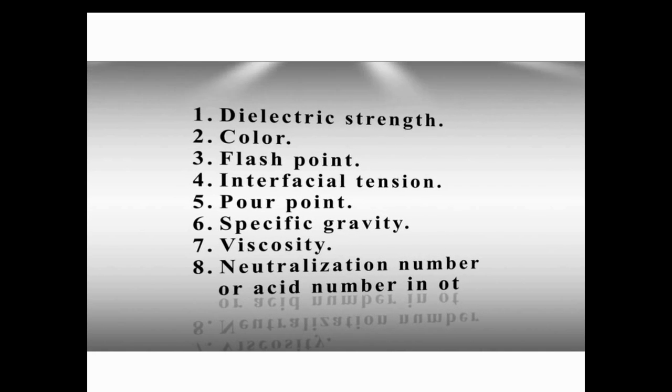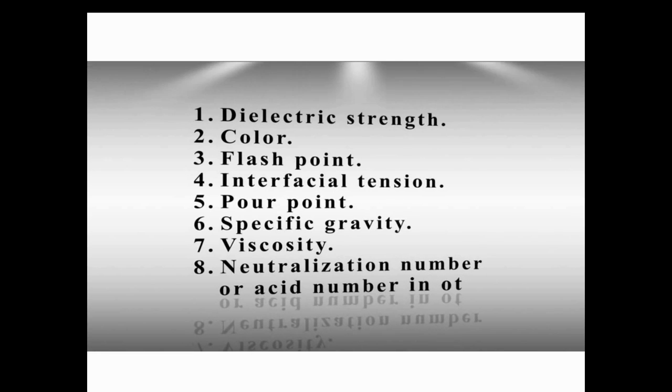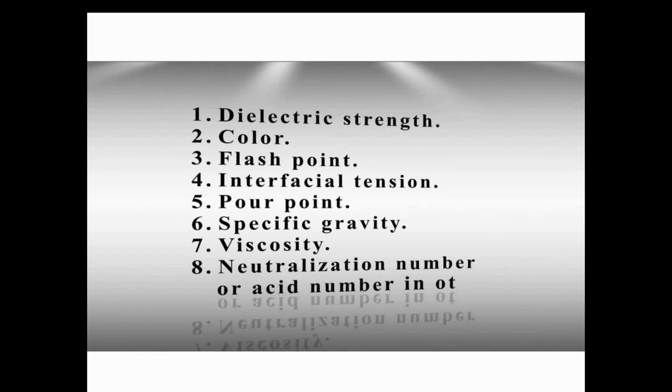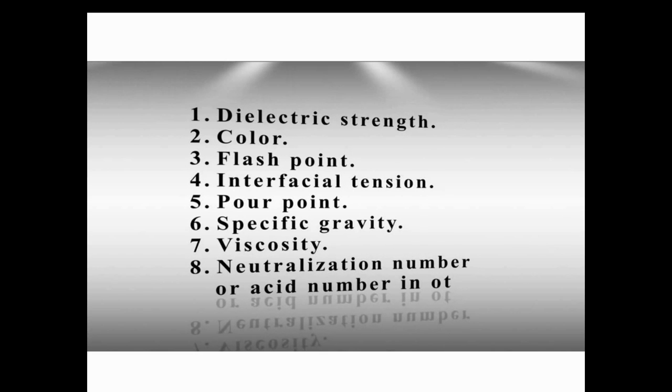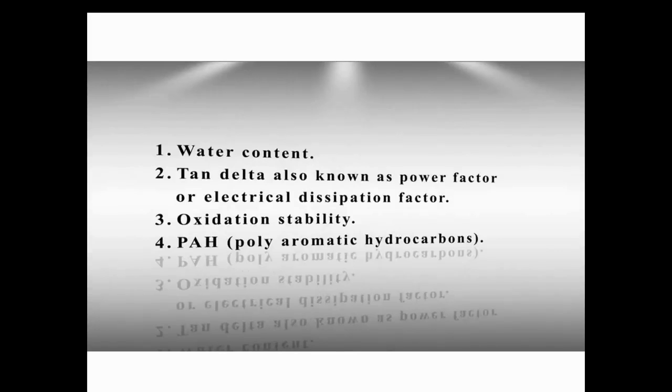But when it comes to regeneration, we consider more factors compared with oil purification or degassing. These factors are water content, tan delta, also known as power factor or electrical dissipation factor, oxidation stability, and polyaromatic hydrocarbons.